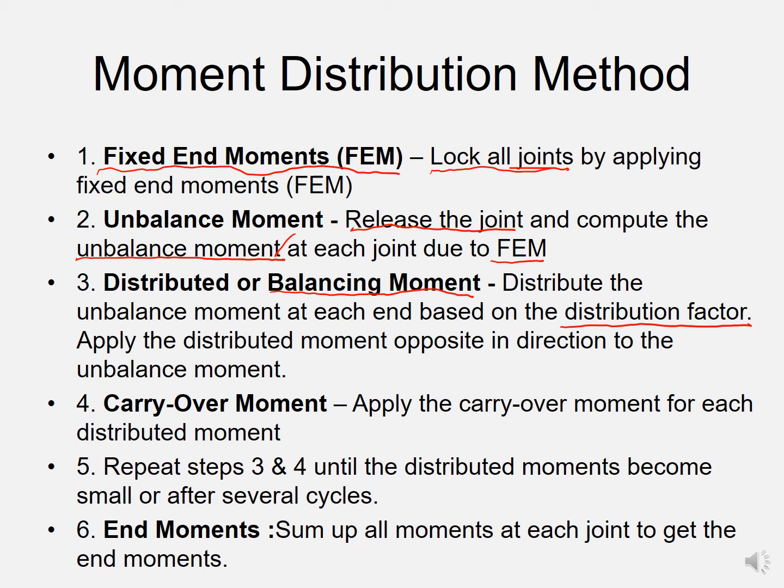Step 4, when you apply a moment at the member, a carryover moment will be induced at the other end by applying the carryover factor, which is equal to 1/2. Steps 4 and 3 are repeated for several cycles or until the distributed moments become negligible or small. After step 5, we can now determine the end moments, which are the same moments we derived in the slope deflection method.